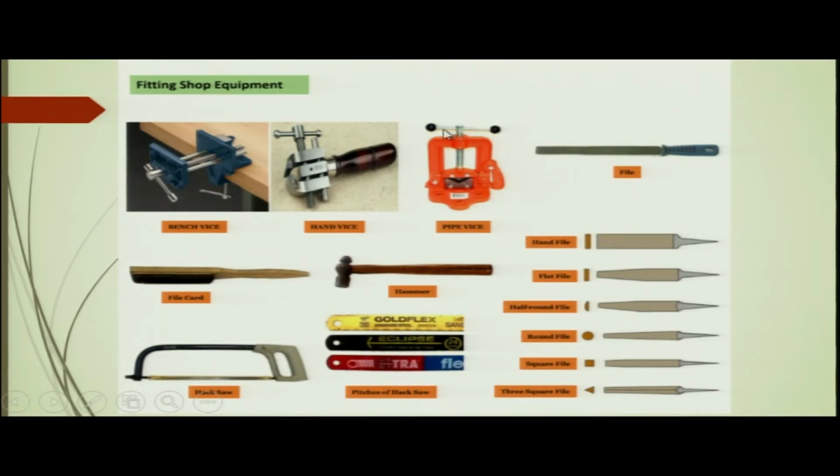On the other end, the lead screw has a handle. Using this handle you can rotate the lead screw. Here inside this is a threaded hole. Through the threaded hole, this lead screw is rotated, and this jaw will go up and down, and within this space then the pipe, there is an attachment for the pipe. Okay. These two attachments are rigidly fixed with the base and with the movable jaw, and within this fixture, the pipe will be clamped by rotating this handle, and the pipe can be cut or the thread can be made on this pipe.